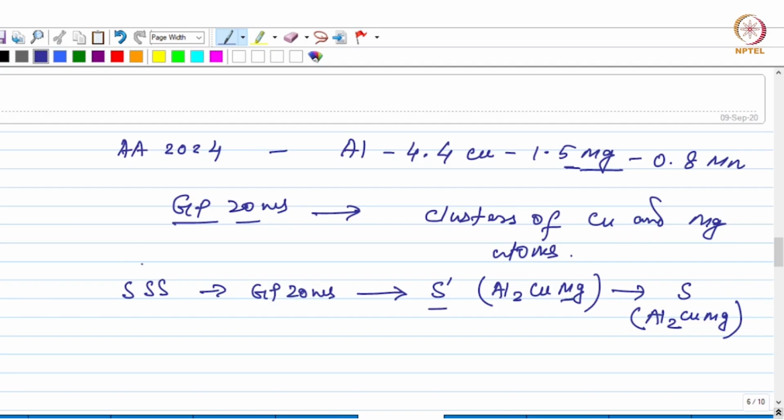And there is a high purity variety of this particular alloy, which is 2124. Here the high purity is maintained by keeping iron and silicon to minimum level. Rest of the composition will remain the same, and these two are kept at minimum to ensure a high fracture toughness.